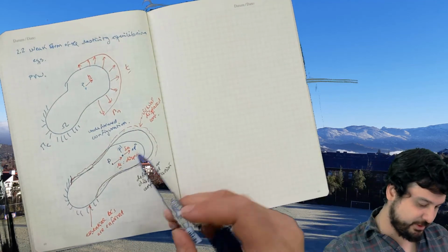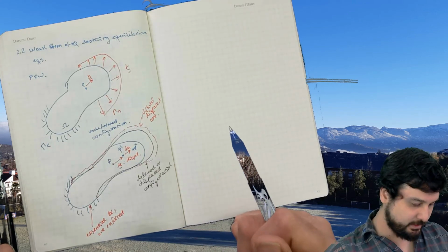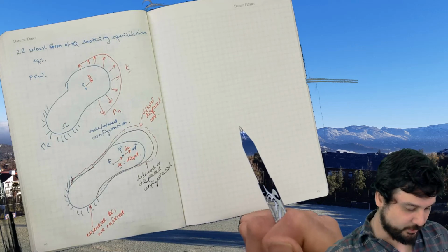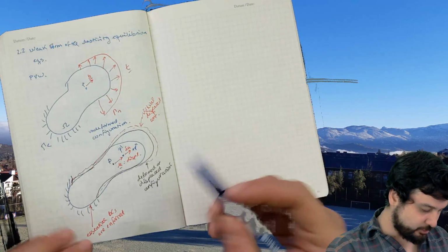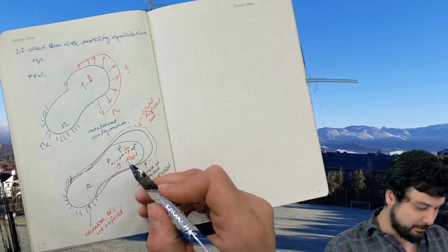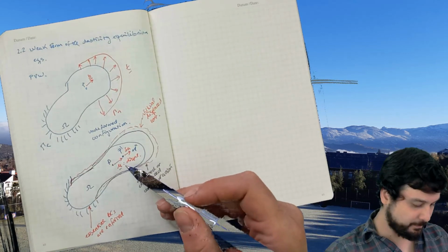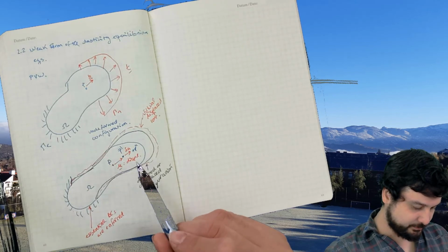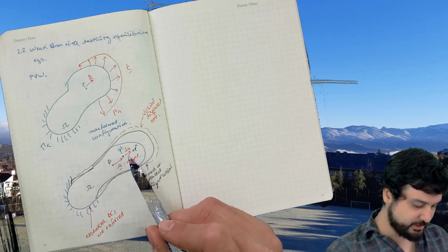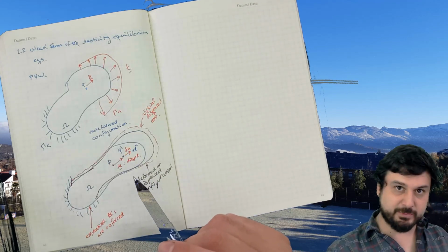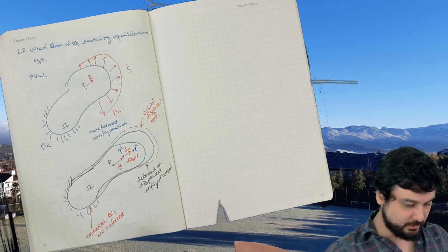Now the thing is, you can choose this delta U, the new shape, the virtual shape you apply. As long as it's small, you can make it whatever you want. So you can displace the domain omega in any way you want about the deformed or displaced configuration, the true solution basically. Then if you compute the work done by the internal forces due to this virtual displacement of the body, it has to equal the external work done.